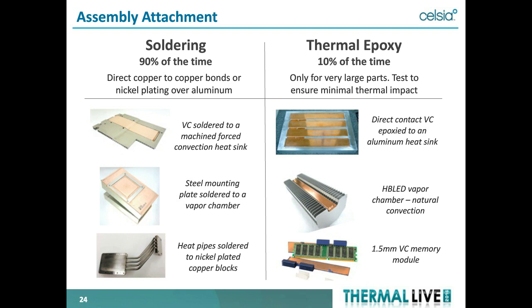Sometimes we will use a thermal epoxy. Often that's used when the power densities are relatively low and the parts are relatively large. So either of those are acceptable. The soldering is going to give you a better performance.